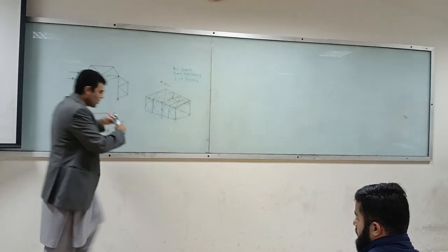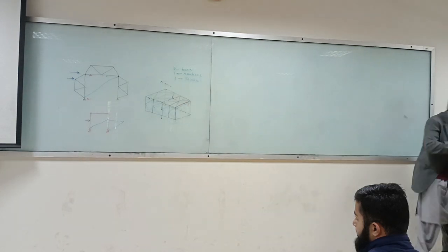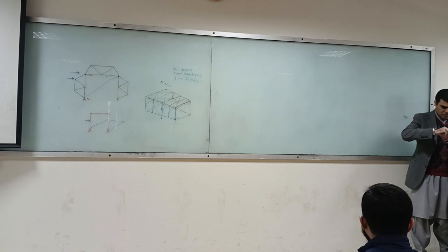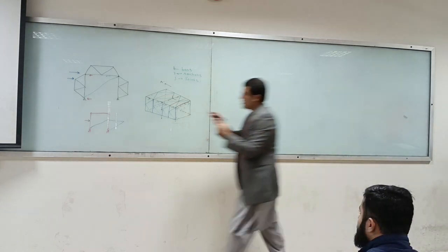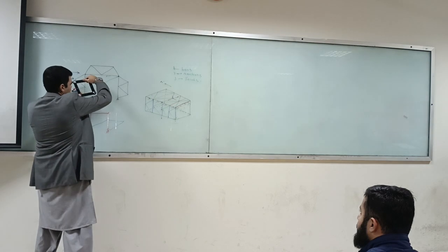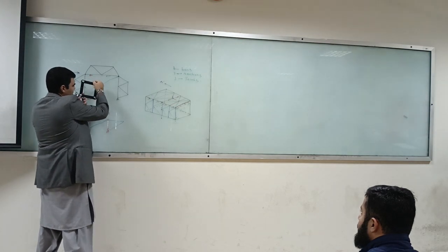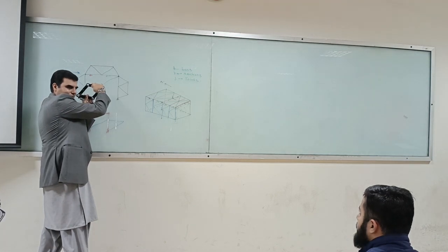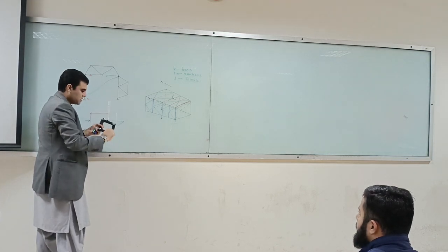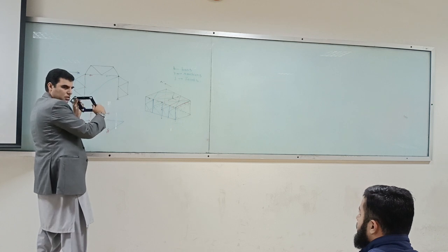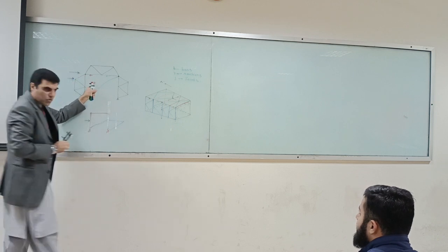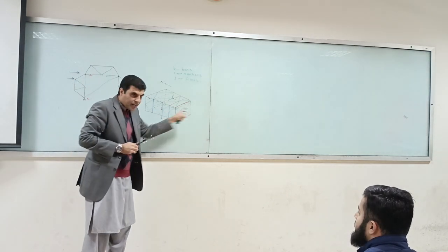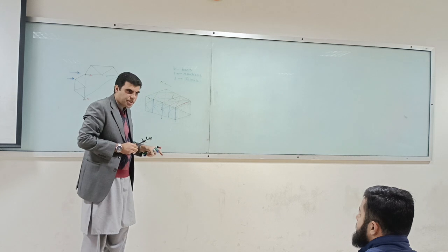Why? Because now your structure has this brace. Now, because of the triangulation, it can take that load. When there was no triangulation, this can fall. So that's what is going on over here. You understand now? So that's why we must have a bracing in this direction.